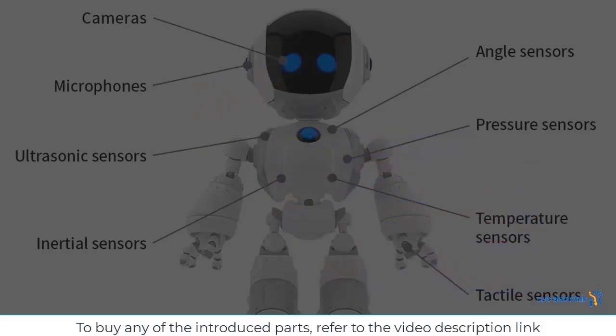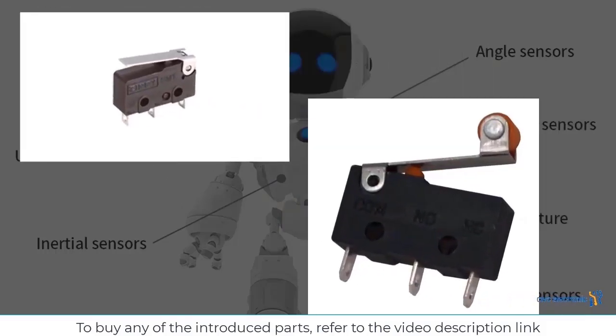Let's move on to the next sensor, and the next most commonly used sensors are microswitches. In fact, microswitches are more of a push button that is used for different parts of the robots. For example, you have designed a robot arm that needs to be driven by a motor and moved a certain distance, and then it stopped. Now, how should the motor detect that it has reached the desired location? Perhaps using motors such as servo motors and an angular movement program, the amount of movement of the arm can be adjusted. But this may also have errors,